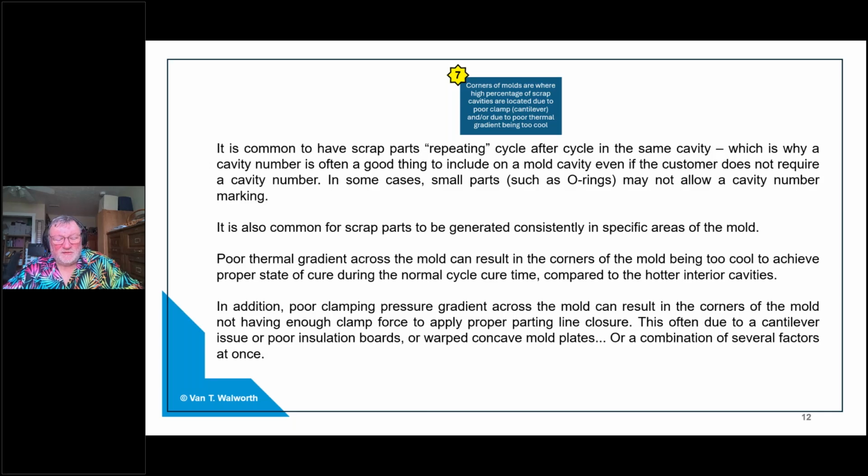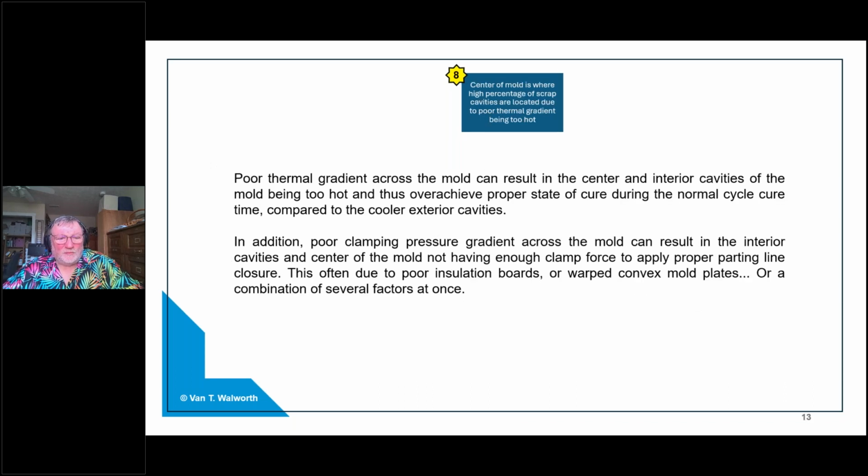But that's an underutilized area, is to either eliminate putting cavities in the corners or to make it easier for those corners to work. In the center of the mold is a little different problem that is underutilized and understood very poorly. And that is the center of the mold is where you can have the most heat.